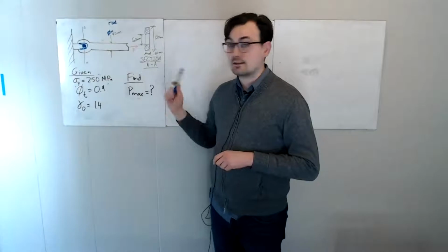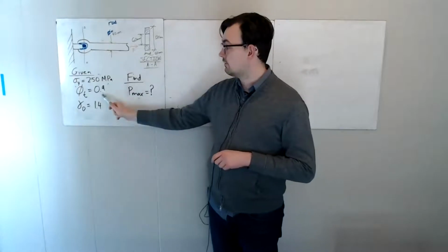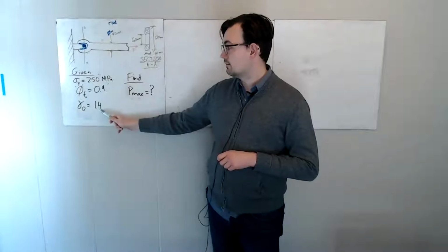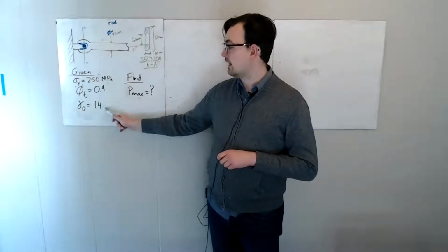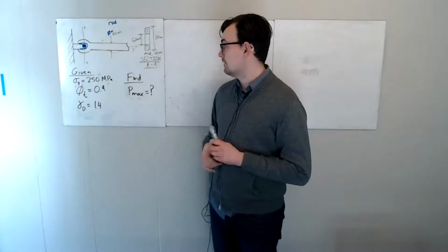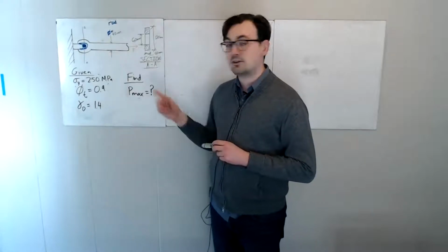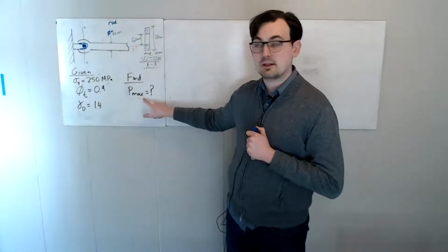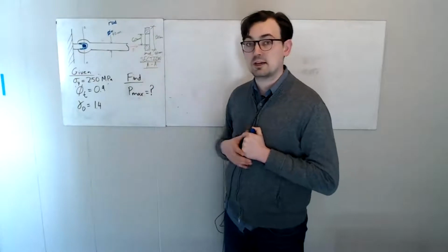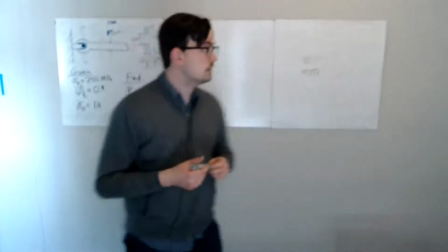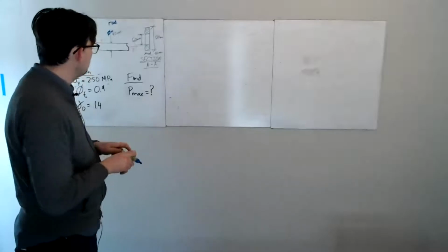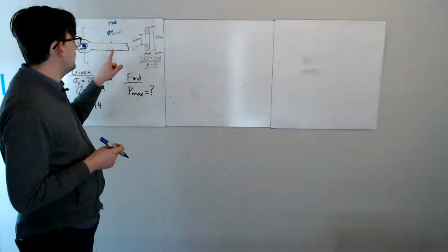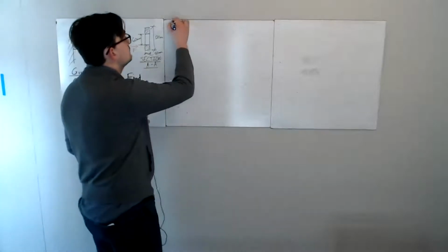We're given, in this case, instead of allowable stress design, our resistance factor, this is phi, and our load factor, gamma. So let's first figure out what our Pmax is. That's our final goal. So we need to check both of those sections. What I like to do is make an assumption. Does it fail at AA or does it fail at our rod? That's our first question.